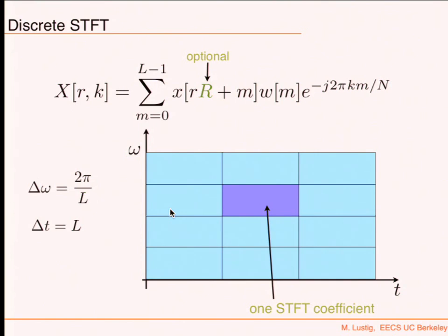If the DFT was just breaking into blocks on top of each other with no time resolution, now because I broke it into smaller parts, it's breaking into this kind of grid, but again the area of each one of them is the same. So I traded off spectral resolution for better temporal resolution. That's exactly what I did.